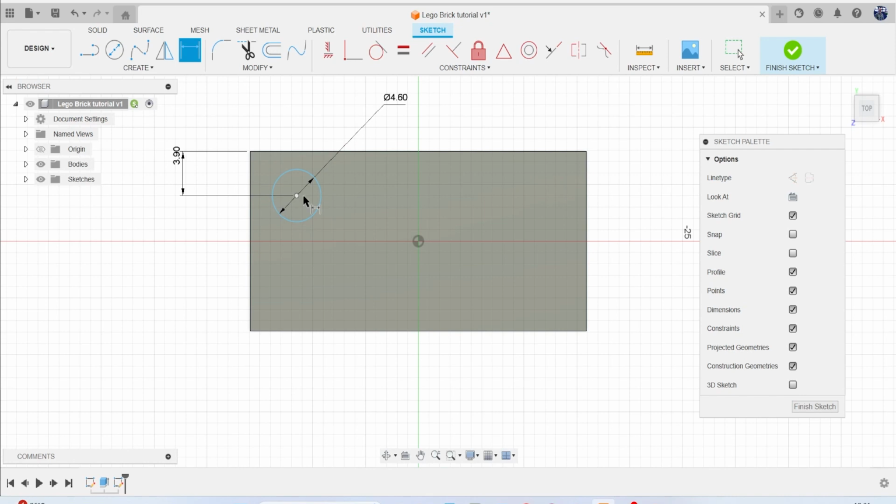Hit enter. And the same from this distance here as well. Now I could do 3.9 there again, but I'm actually going to click on this here and hit enter. So that's exactly right, because what could happen now is this is the main dimension and everything else is going to copy that. So if I change this later to like 5, it's going to do it evenly and it'll update there. And do 3.9.